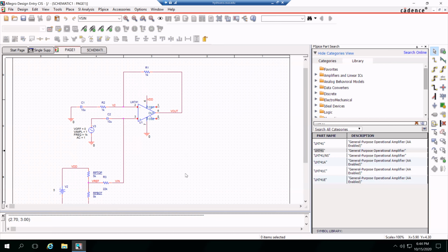Well, you know, I'll draw these out. I'm going to put them in the slides for you with the equations, and I'll post it on the page. But there's an inverse relationship between frequency and impedance, right? In this equation, because it's 1 over 2 pi FC equals a resistance. So really it's F equals 1 over 2 pi RC, right? So the lower the R is, the higher F is. So that's why they have you calculate the minimum. So you know that's like your worst case condition, right? If this wiper is at VDD, then your frequency needs to at least be above that in order to get everything to work. So that's just kind of like a rule of thumb for you to work off of.